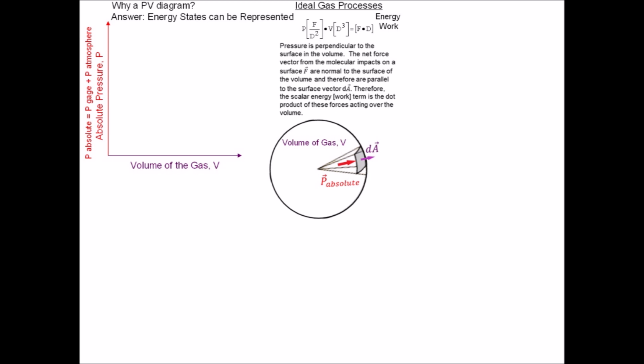For these videos, we'll only be talking about closed systems. Closed systems are systems in which there is no flow of gas into or out of what we define as the system. Therefore, there's a constant number of moles or molecules of this defined gas comprising a single homogeneous volume within that system. If during the process the volume increases as shown, then the closed system inside that volume will do positive work on the surroundings at the boundary interface between the system and its surroundings.